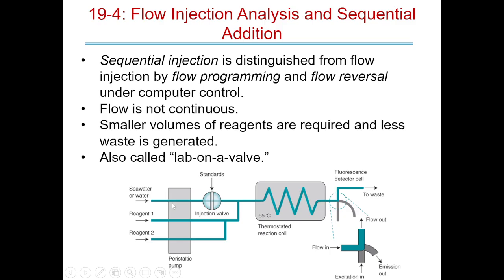So this is a peristaltic pump, and these are these precision pumps we were talking about that take out specific amounts of each one, okay? And you can program to do it. So you'll have a seawater or water sample right here. This is going to come in with reagent 1 and reagent 2. Notice that this is going to be your injection valve right here. So you'll put in standards here, etc. Okay?